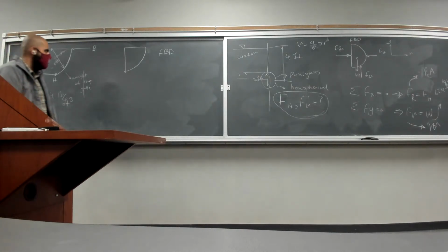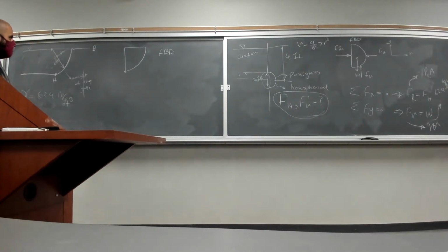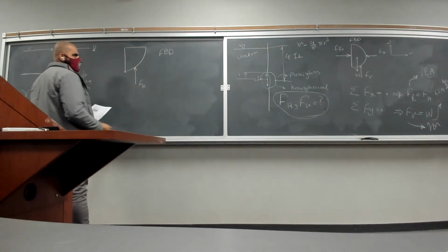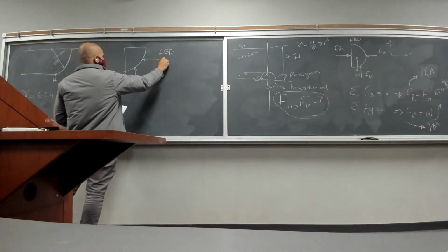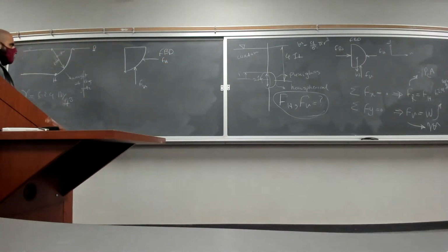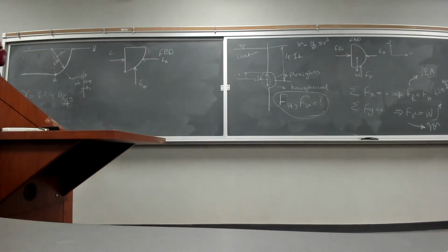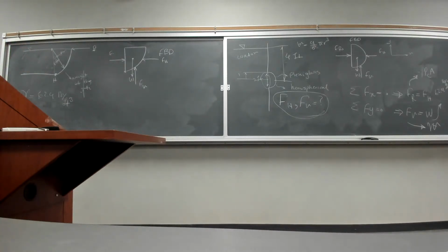Okay, so let's solve the problem. What are the forces that are present here? The first two are actually going to be your vertical force and the horizontal force that are being exerted by the gate to this body of water, right? And we also have the force that is being exerted by the rest of this body of water. Let's call that F1. What else do we have? We have weights. And that's it. Do we have any other forces here?